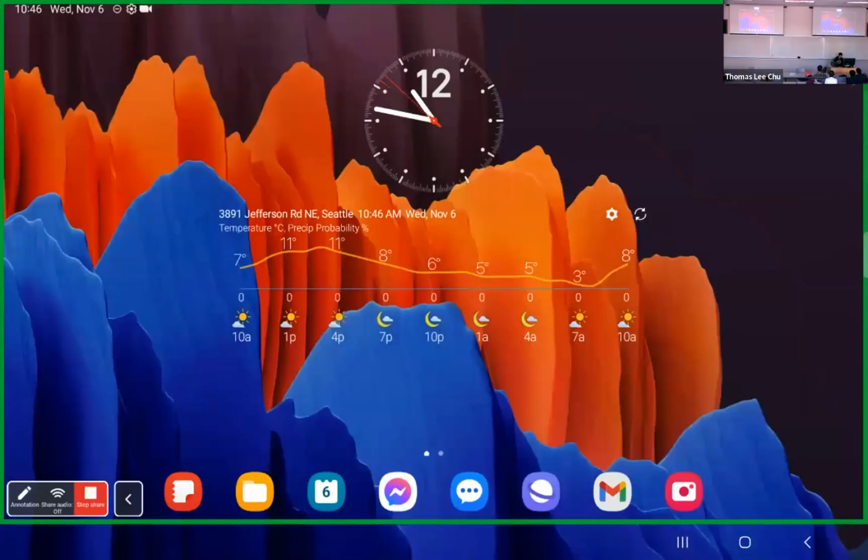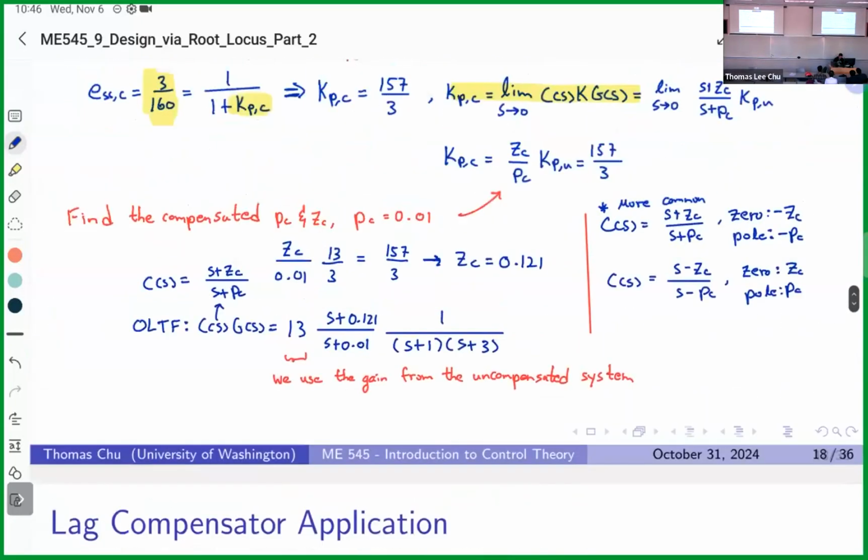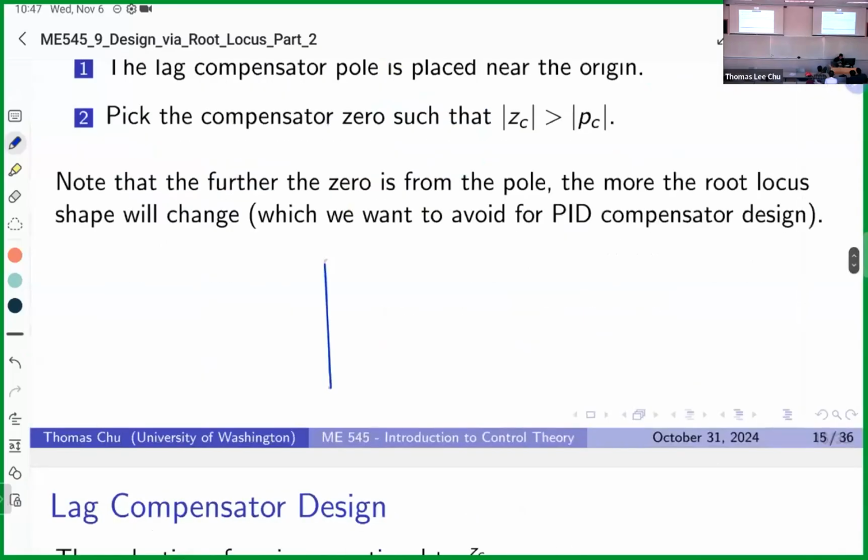So one other thing about PI controllers as well is that sometimes we might see, and maybe I'll draw this out in the lag compensator design as well, a response that looks like this, like that, where if it weren't for that third pole, this would be our percent overshoot, this would be our peak. I don't think the textbook defines it, but I like to call it a local peak. That's where we get that overshoot.